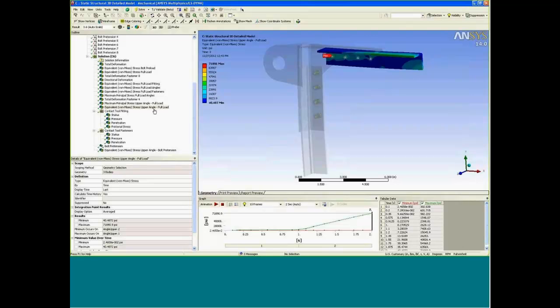One thing you want to do with the multiple load step analysis is keep check on the substep, or I'm sorry, the load step you are post-processing. That's identified in the time item in the legend, and you can select which display you'd like to show by selecting the individual time point in the tabular data.